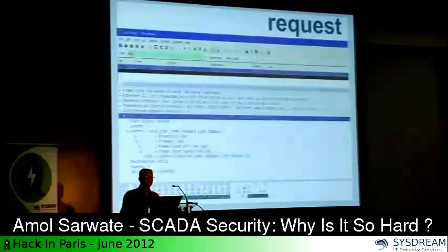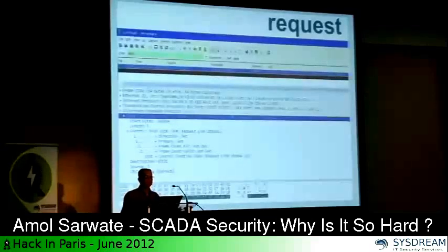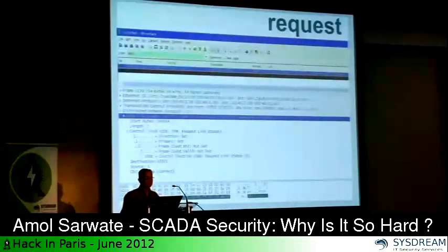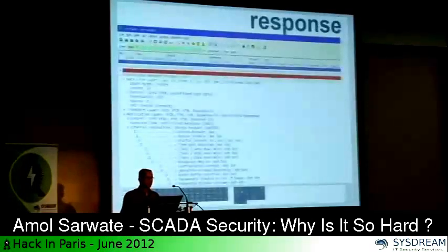What you see is a request, and again, Wireshark or many of these sniffers already have protocol decoders for a lot of SCADA protocols. So in this case, we didn't write any custom plugins for Wireshark. You send in your request, you see the request going. This is basically a request of the data link layer to just get the status of the line. What's the status of the line? You get a response with several bits, and each of these bits would correspond to something in that environment.